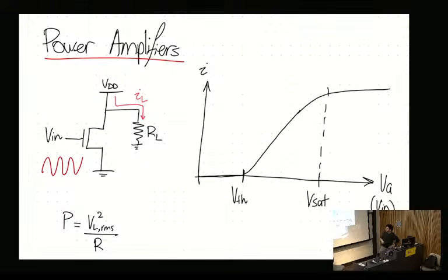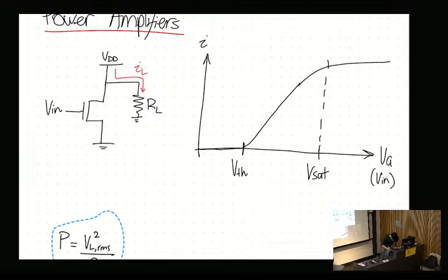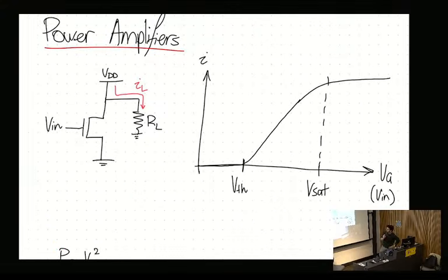Okay? So with a high enough DC signal at the gate of the MOSFET, we turn it on, and then current can flow through the FET, and then eventually it saturates. Now, let me just remove this for now, just give myself some space. What dictates the class of operation of the amplifier is specifically where on this curve we start the amplifier. So where is our steady state for the amplifier? That is the class of operation.